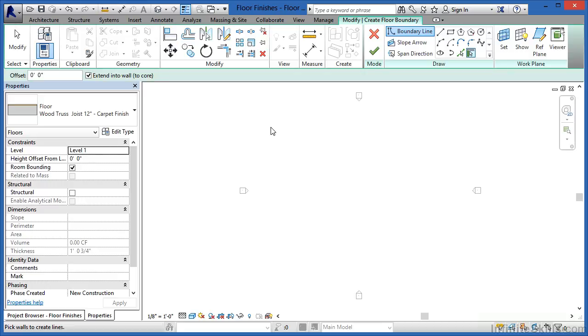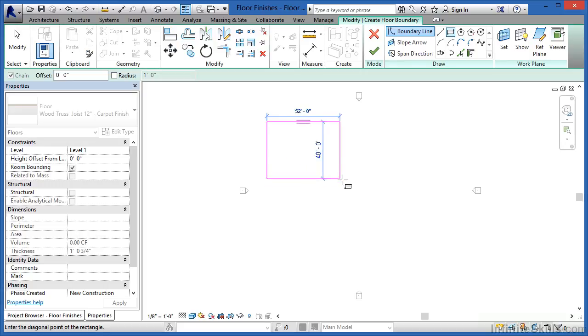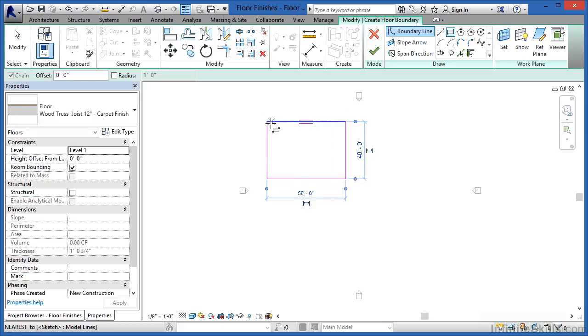From here, we want to draw in a floor, rectangular shape, right in this area. So, pick on the Rectangle tool, click over here in the Drawing area, then draw in a rectangular shape. Now, the exact size of this doesn't really matter. I'm just going to make it roughly this size and then click in order to place that exterior boundary around the outside of our floor. From here, I'm going to click on the big green check mark to finish up the floor.